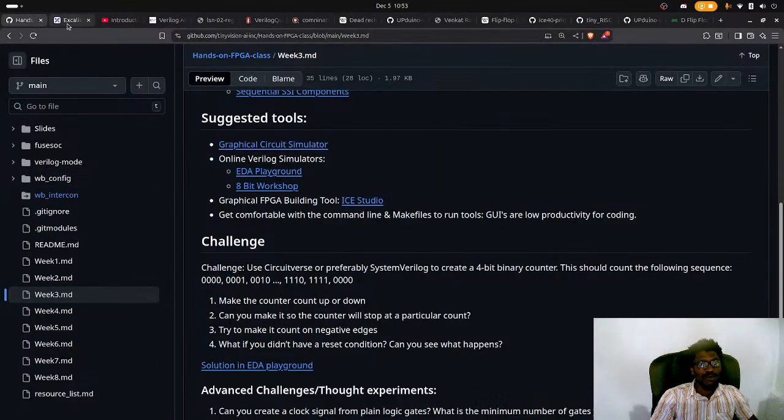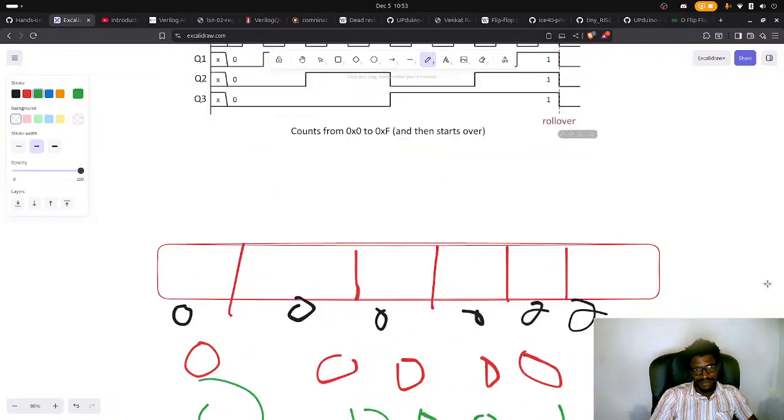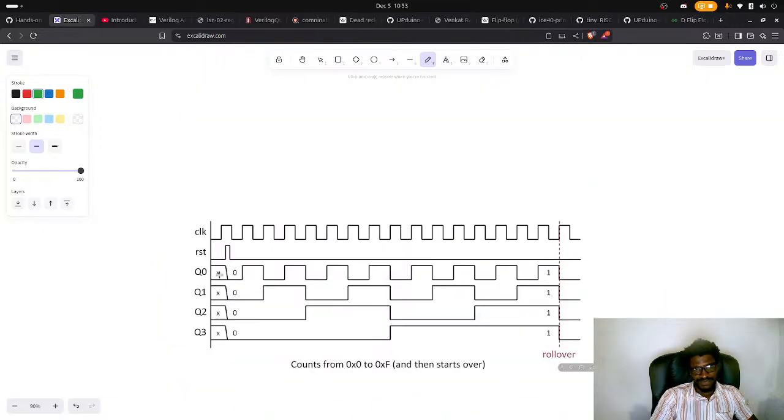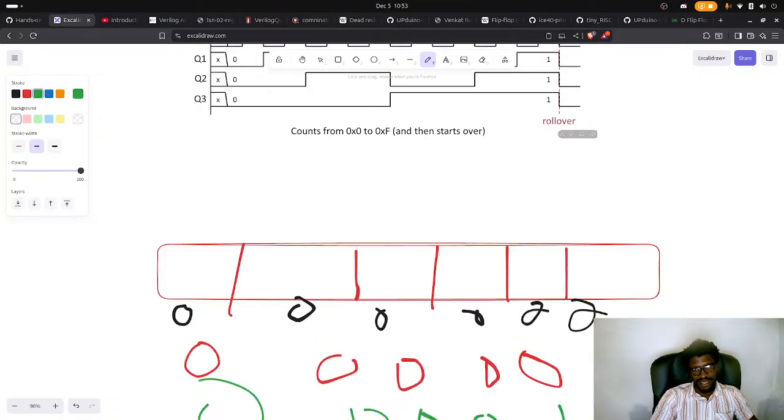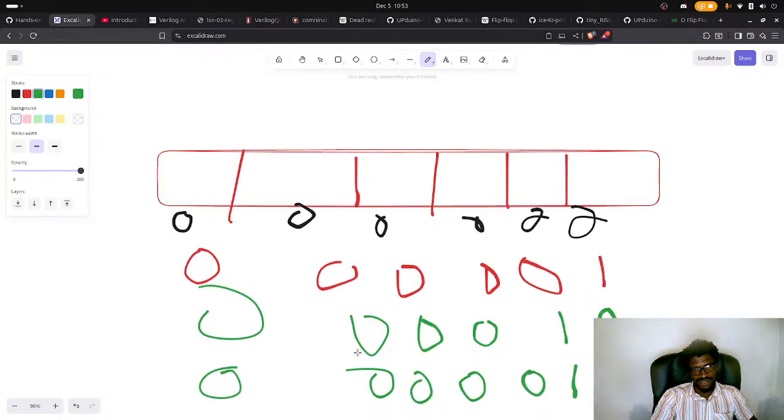So let's look at a 4-bit binary counter and how it works, and then we can stop there, because we've already looked at a binary counter here. This was a 1, 2, 3, 4, 5, 6 binary counter. So look at it here. We have some sort of clock signal that is coming in at a certain stable rate. And for every one of these clock signals, remember what we're doing here. We're adding 1. Every time we're adding 1 into this thing.